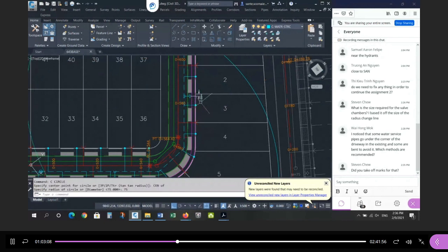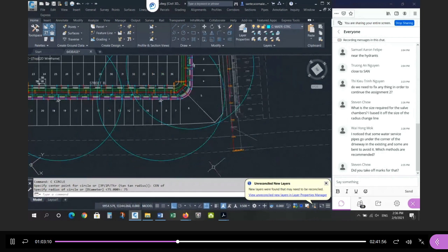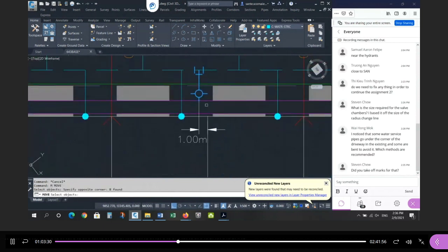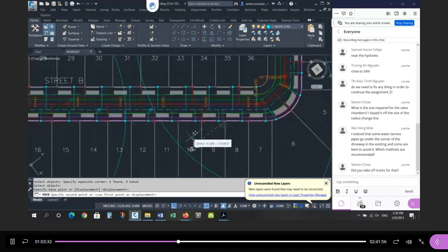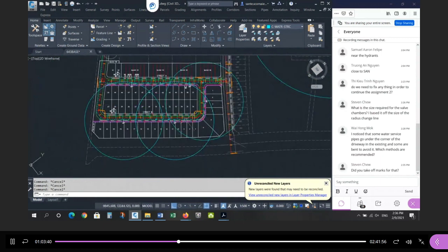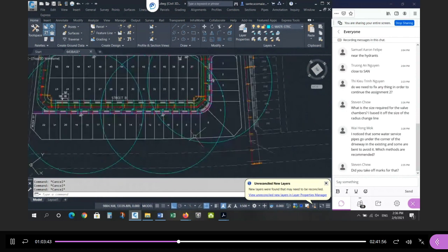So this has to be 75. So you're going to need 3 hydrants on Street B, and now this one can move over, right? It doesn't have to be exactly where I put them. I can move this over 1 unit or 2 units and still have coverage. Extra overlap here, a little less overlap here. So instead of putting it here, I can put it here. So I'm going to move the hydrant with the dimension line from here. I'll put it over here. That's the center of this circle, and I still have coverage. And that might be a better distribution. So there's more than one solution.